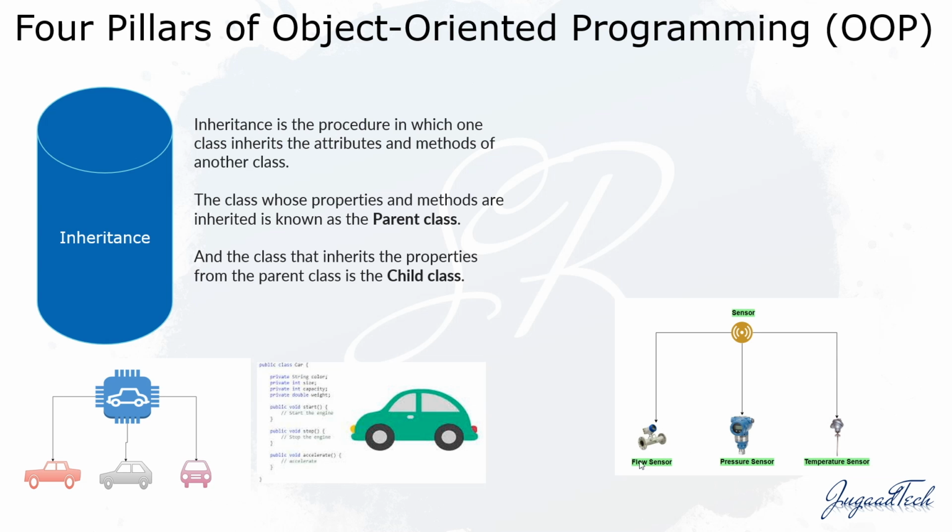So let's see exactly how it gets incorporated into the PLC code. When we read the data from any sensor, the first thing we do is a scaling in the PLC code.